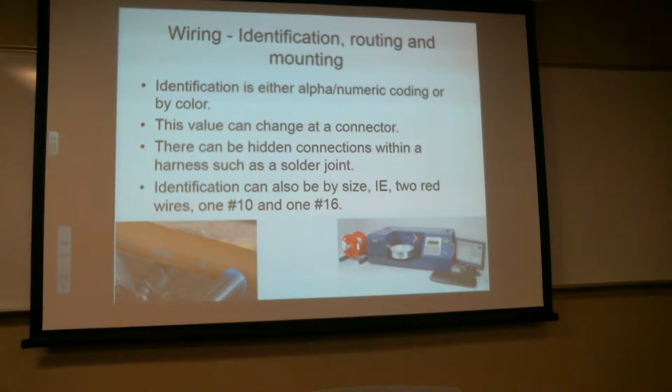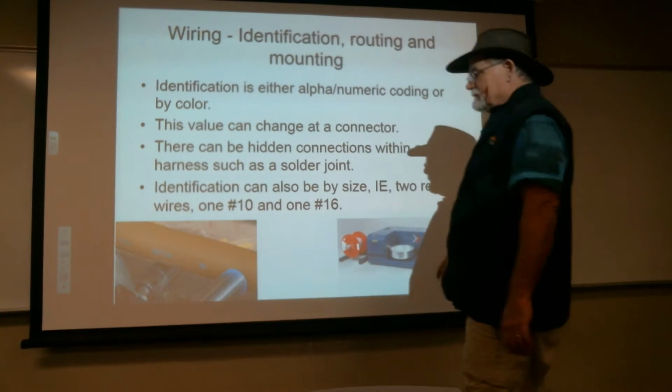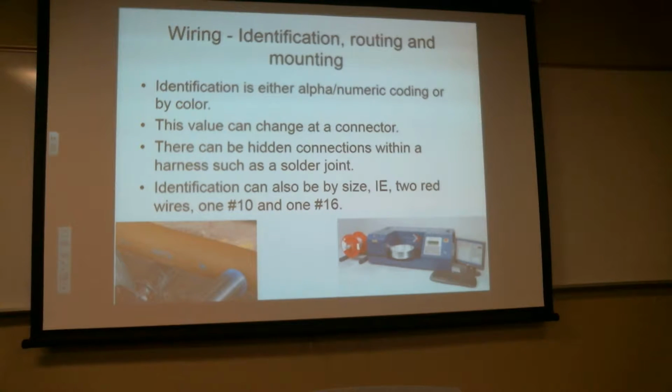Now that's changed in the last 10 or 15 years where you can buy mil-spec colored wires. They cost more, in some cases by a substantial amount, versus buying yourself a decent labeling machine that not only will label the wire, but if it's a sophisticated one, you can program it to label the wire as it's streaming it out and cutting it off and stripping the ends for you. Well, that's a much better way to go. So you still see white wires being used a lot, but there is some color coding with a limited amount of color. Just because it's color coded doesn't mean it doesn't need to be labeled. And labeling is required in aviation wiring.